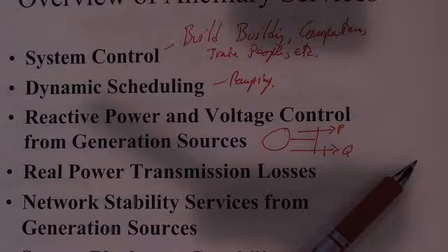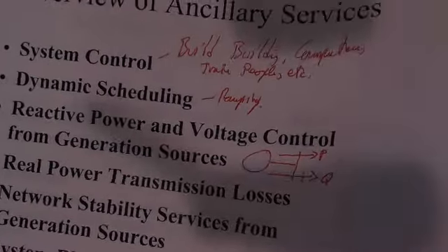The truth be told, the way that you get it to push reactive power into the network is by raising the voltage, which involves increasing the current flow on the rotor of a standard generator, and that increases the field, and that causes the more reactive power to go out into the network. It also is a way of regulating the voltage. So if I want to regulate the voltage on the power system, the primary way that I regulate the voltage is by the generators.